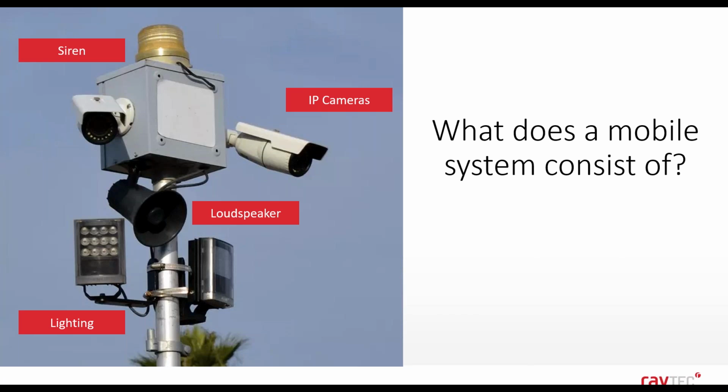Along a similar line, you could have a siren. So very much the same sort of deal as a loudspeaker, but just to be a little bit more obtrusive, or if that's the correct word, and make people very well aware that they shouldn't be there. Perhaps you also have other things such as detection. So you might have an Optex Redwall, for example, to surveil or act as detection alongside a building, or use other sorts of PIR detection systems or lasers.